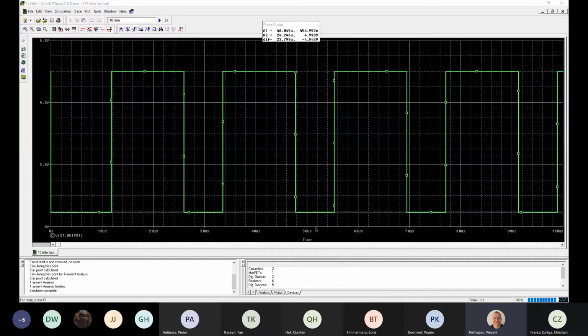So now you know the frequency of the signal that this circuit generates with the values of RA, RB, and C1, which you've just set in your circuit at PSpice. You just measured with your probe cursor window that one wave shape takes approximately, it's an approximation, about 21 microseconds. If you want to know the frequency, you just divide 1 by 21 microseconds, which equals the frequency of this signal in hertz. Once again, I wrote all these steps down in the course document, so everyone can read the information in the document. And that's how you can check from your simulation whether it works like that with these specific values for RA, RB, and C1. You understand that, Christian? Yes.